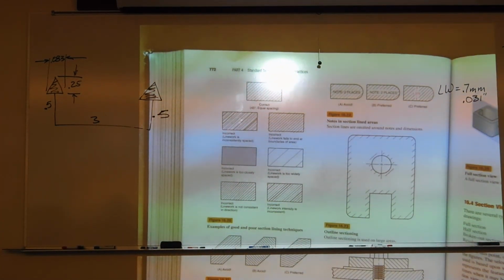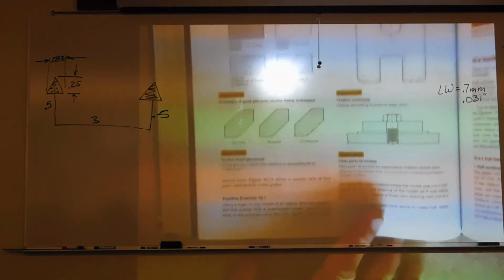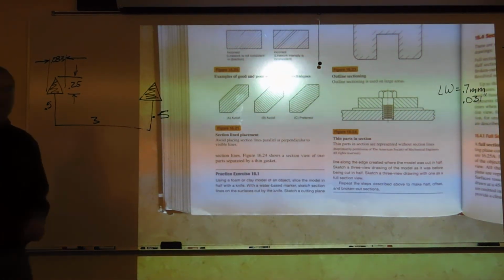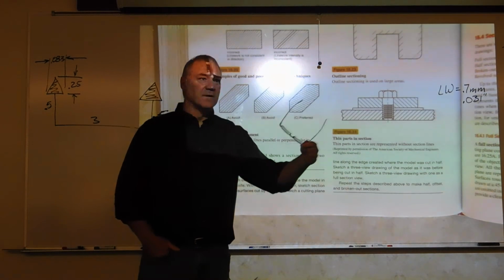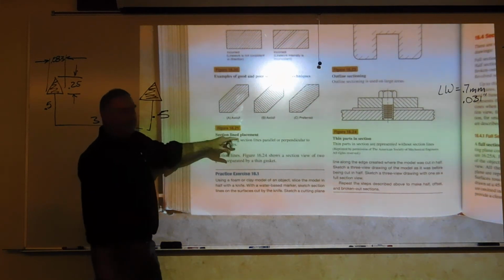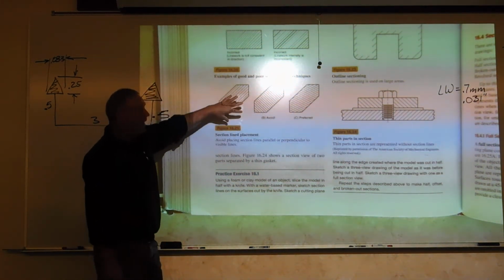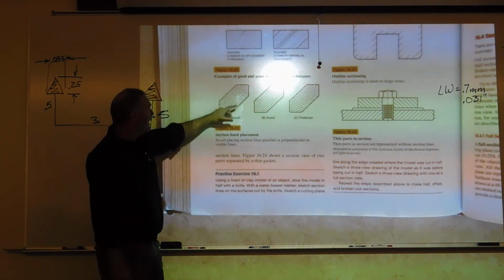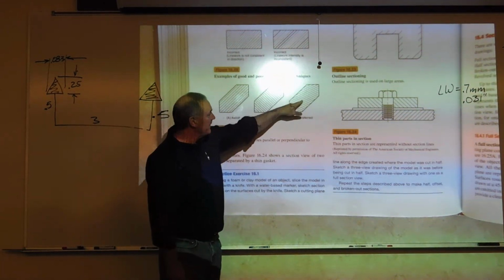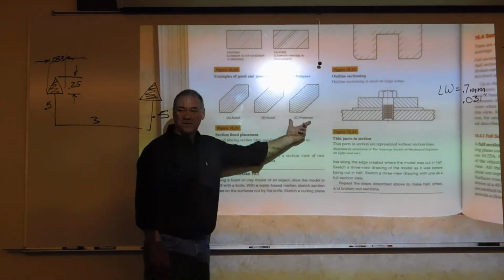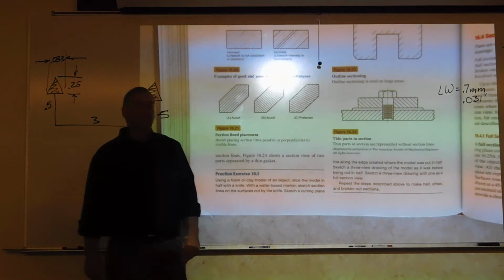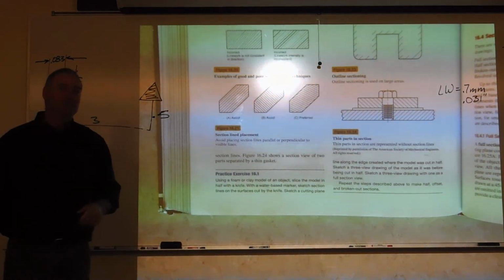One other thing on your hatch patterns when you produce them, let's go to the figure right below, is you do want an angle change off of your object line so that people don't confuse this thin line for something else. So like on this one where my lines are kind of coming at 45, they put a 45-degree hatch in here, I would rotate that hatch. Get it off of that. Get another 15, 20 degrees off of it. I think the author rotated that one about 15 back to a 30-degree angle and is saying this is preferred. It doesn't matter which way you go, just get off of the angle of the object lines around it so that it stands out as a pattern.